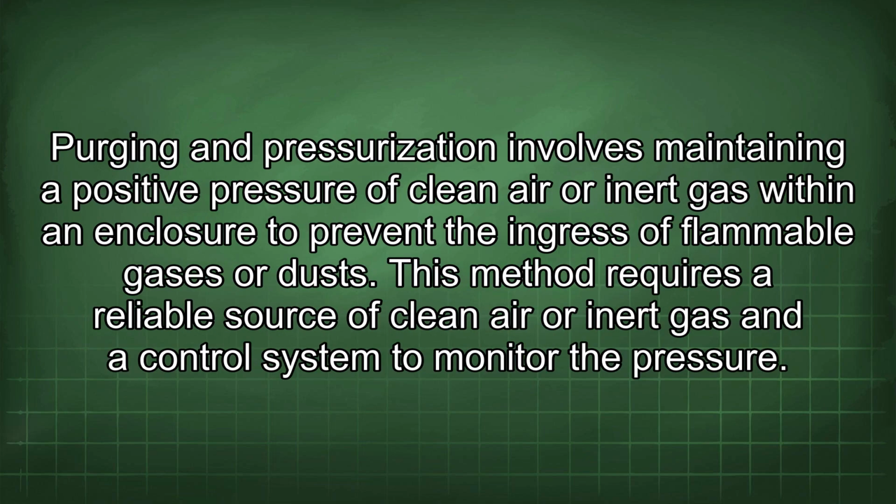Purging and pressurization involves maintaining a positive pressure of clean air or inert gas within an enclosure to prevent the ingress of flammable gases or dusts. This method requires a reliable source of clean air or inert gas and a control system to monitor the pressure.